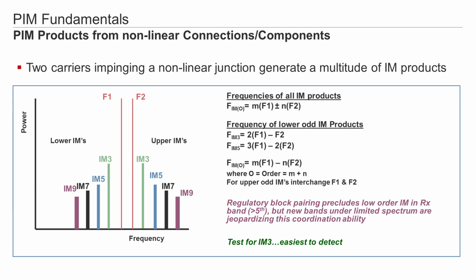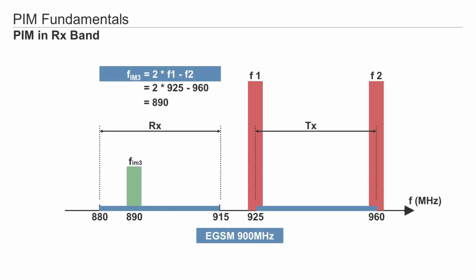But why is all this discussion so important to the wireless industry? We already mentioned that PIM is a source of interference for mobile base station system installations. The base station sends out high power signals to users' mobile devices, for example 2 times 20 watts per carrier. Users' mobile devices also send information back to the base station. However, these signals are very low.